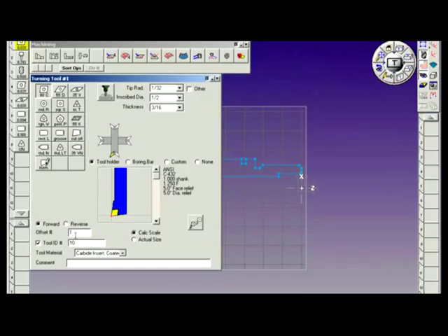10 and the offset 10. When we generate the code, it's going to give us a tool 10 offset number 10. If it's in a different position, we can change the tool ID number and the code will output T6 offset 6. If tool ID is not selected, the tool call in the code is based on the position in the tool list.